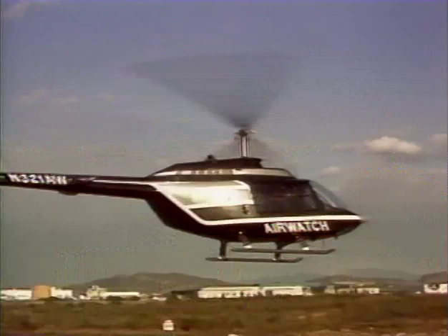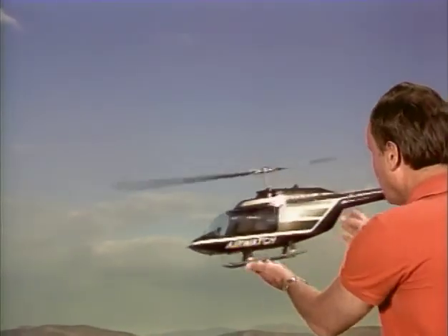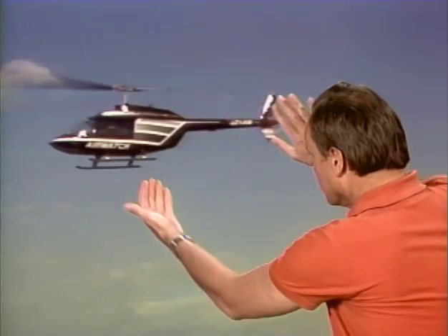Now, the tail rotor blades compensate for that torque, and they're going to ask you what happens if you have a decrease in the pitch angle of tail rotor blades. And the answer is that the tail tends to pivot in the direction of torque rotation around the main rotor axis.